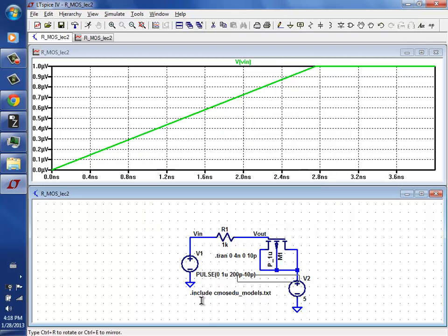What happens is, this program was made for simulating switching power supplies. Switching power supplies have the unique characteristic that really fast things are happening on short time scales, but the switching power supply operates on a long time scale. In order to keep the simulation data and response short, they play some games with the plotting and what they store. In order to avoid that, you can put this option in there too, so it doesn't do that. And so now you see the step response, just in case you had that issue.